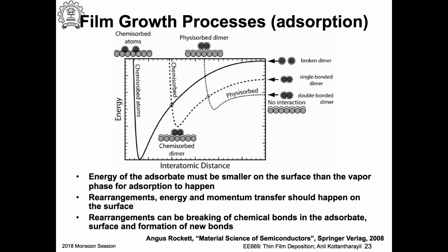So these things can be controlled in deposition by controlling the temperature, or if you're using plasma, I can use particles in the plasma. For example, if I have argon, argon does not chemically react with the substrate, but it can bombard the surface, right? So let's say I bring in a material that I want to deposit on the surface, and I get a dimer of this material, but then argon ions break this into monomers, for example.